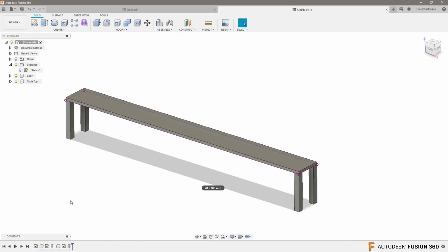Now, you are right, Kim, that these down here get extremely long. What you can do is group them together down here, but you can only group in a certain order. What I mean by that is I can take these 3 that were created and belong together. And by the way, if I click on this sketch, notice how it shows with 3 lines that component it lives within, that body. So you get that indication when you click on a sketch.